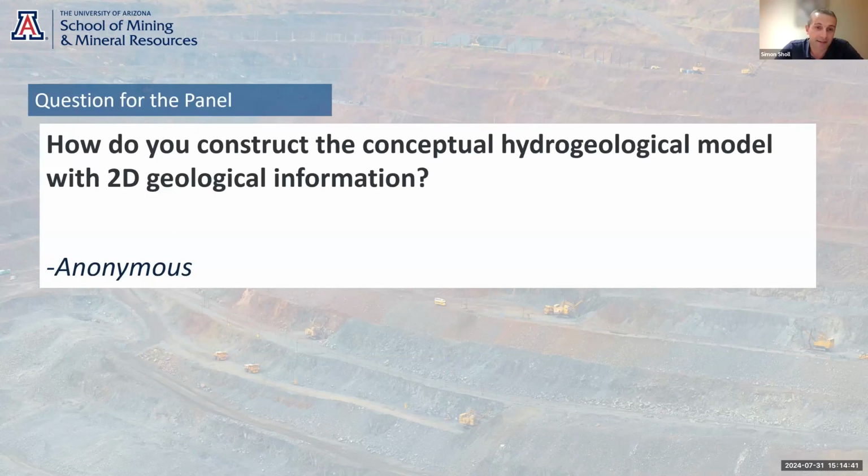You need to be getting 3D information, but you also have to do the best with the data that you've got. The whole point of a conceptual model is that you use as much information as you possibly can to describe the situation, and then you test that, with boreholes or pumping tests or taking flows from rivers or whatever that might be, and then you refine that conceptual model. The conceptual model is never finished. There's always something new. Yep, that's a good point, Simon.